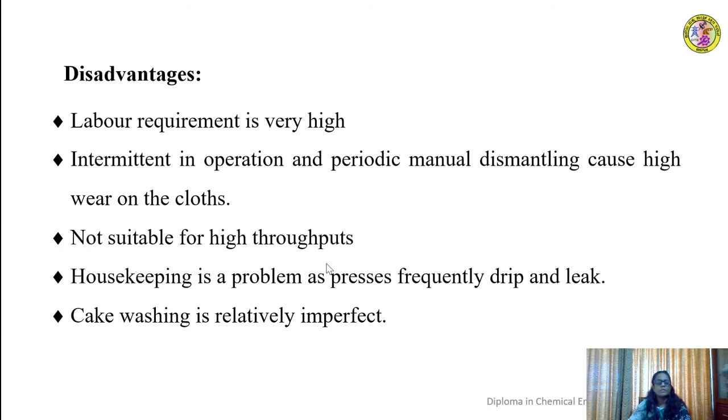It is not suitable for high throughputs, and housekeeping is a problem as it frequently drips and leaks. So there is a continuous process of arranging, assembling, dismantling, and all that. So because of that, the filter press keeps leaking or dripping on the floor surface, creating a housekeeping problem.